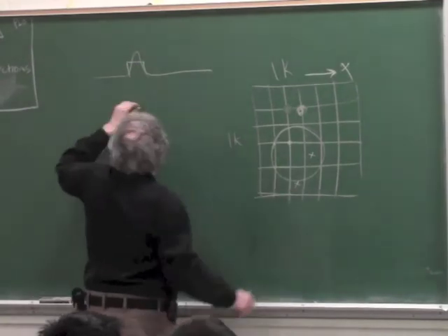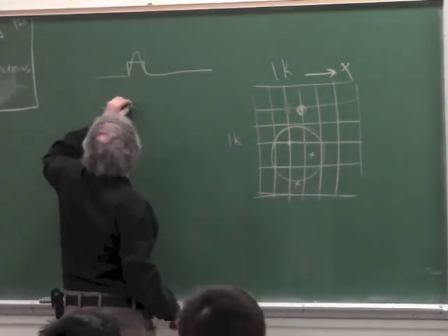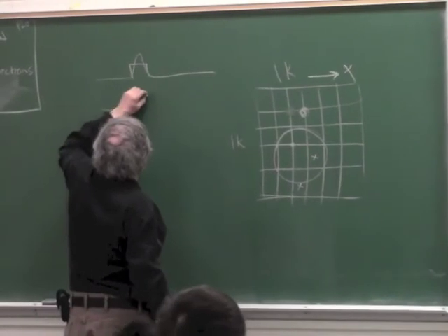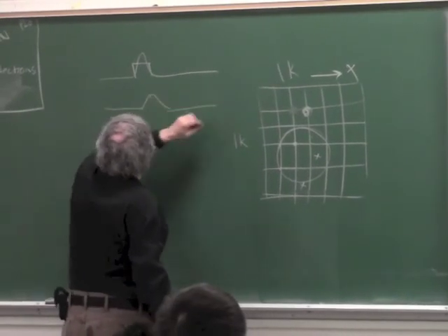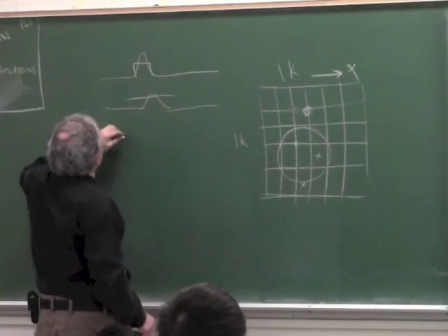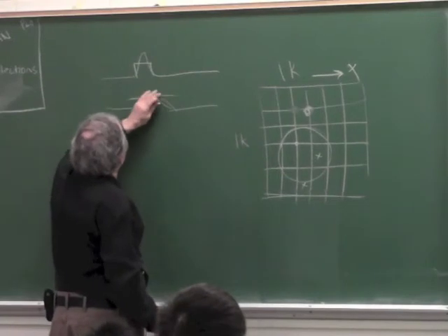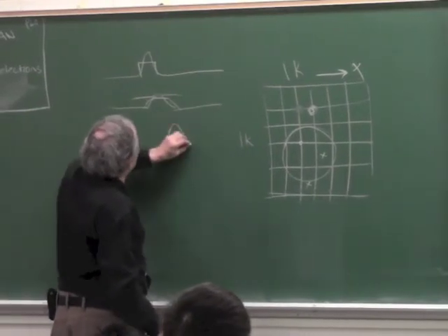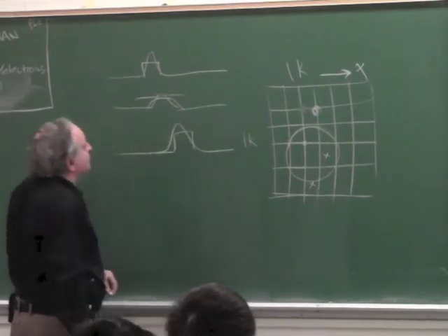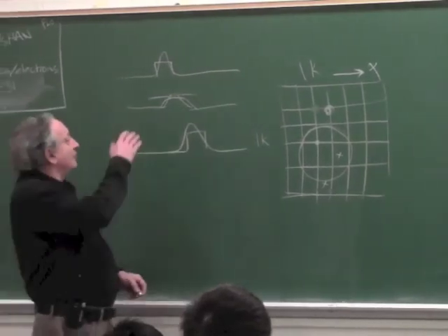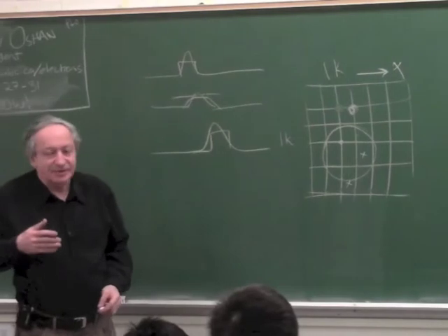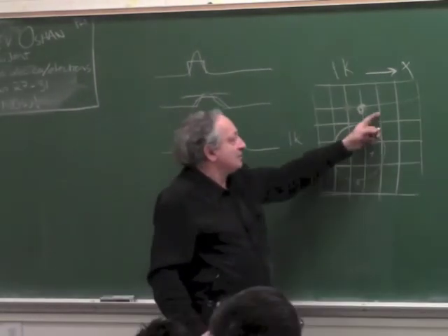If the spot moves, the second readout, maybe in the middle, you'll get something like this when it hits 2 cells, and then it wouldn't reach the threshold because it will be too wide and low, and then it will move to the next cell, and you'll quantize it. So if you convert it to binary early quantization, you'll only be able to have 1,000 positions,